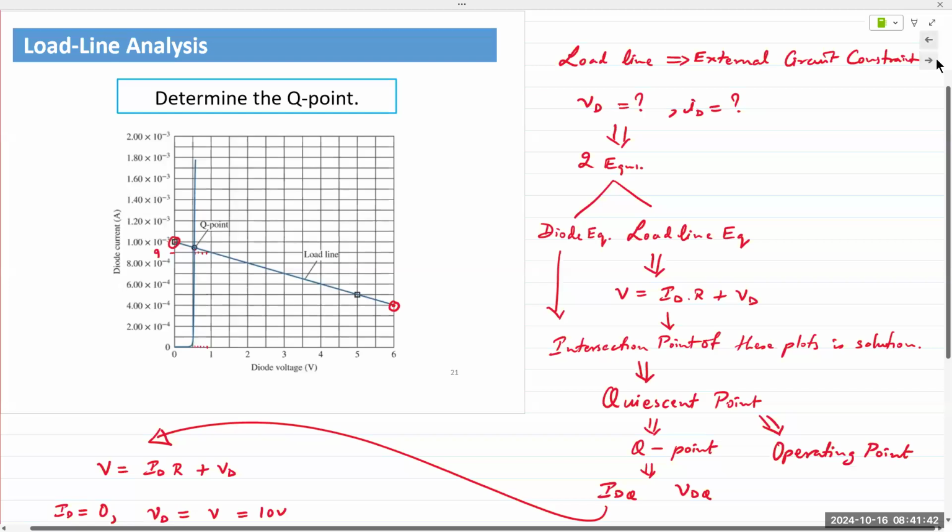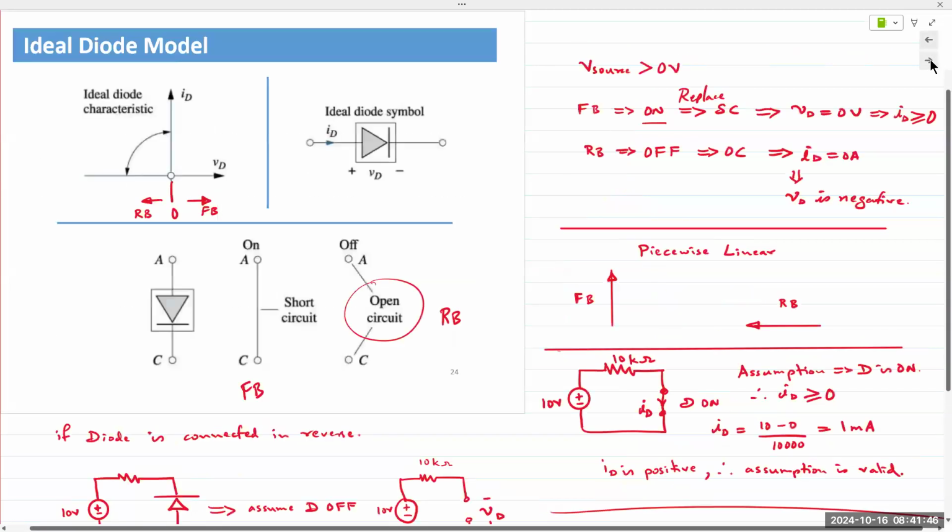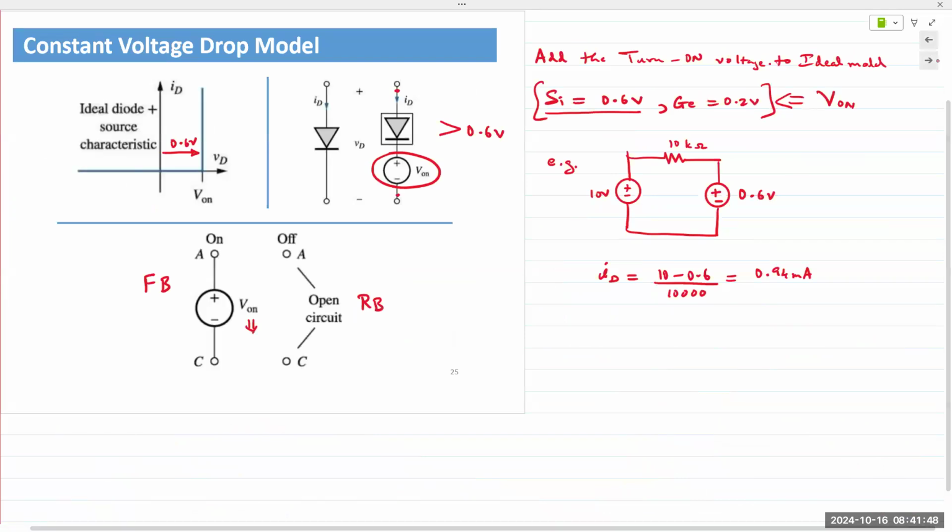Right there, 0.94. So the ideal diode is a very quick analysis. I wouldn't say easy, but quick, right? On, off, zero or reverse bias. But when we add in practical effects with the voltage drop, we can get an even more accurate prediction of our values. All right, 10-second pause. Let me know if you have any questions.